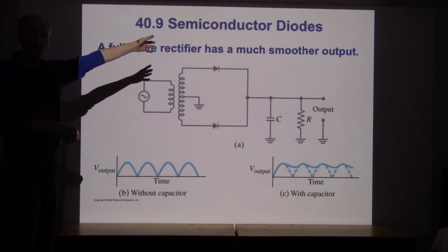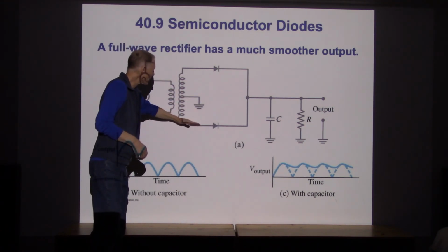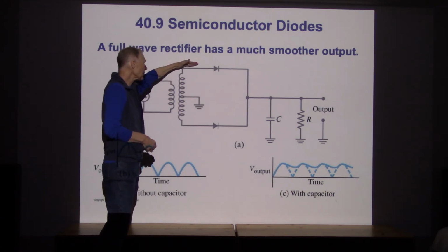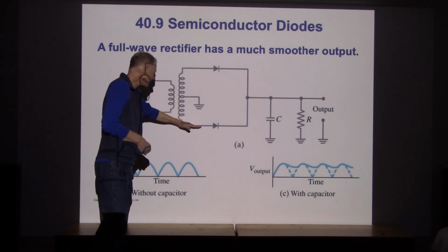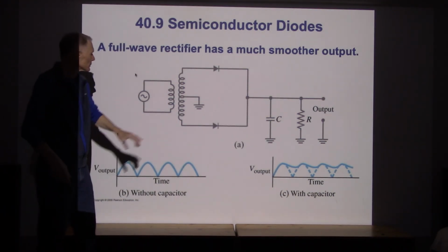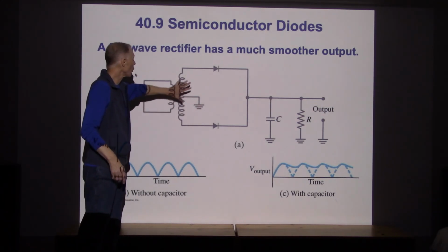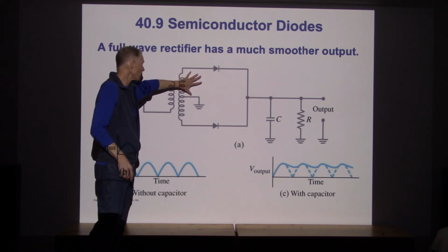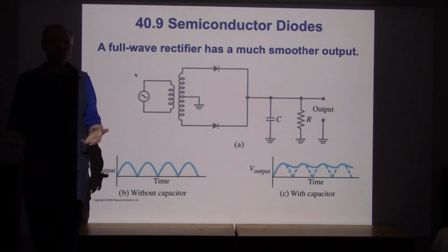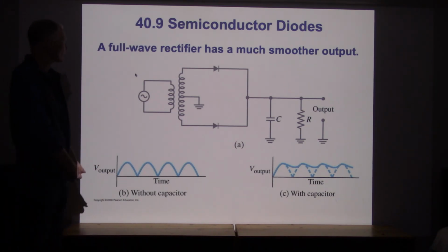So those transformers up on the power lines, and then the 3 wires coming into your house are these 3. There's a neutral line, a hot line, and another hot line here. If I connect up circuits using the ground and one of the hot lines, that's 120 volts, or I can do the same thing here, I get 120 volts here. But if I use these two, those are the lines we use to set up 240 volts in our house. Anyway, just a quick aside from Physics 4B.